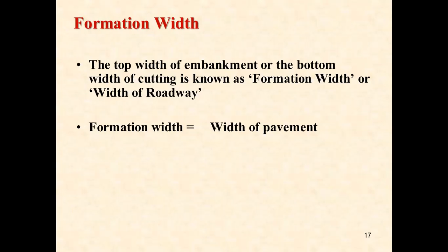So we have to go for land acquisition, and we have to give compensation wherever property is there, for the facility where we extend the roadway. So this is going to occur. That's why we take into consideration the future of 5 to 10 years. The formation width is acquired. The land is acquired for the total width of the formation, which we call the width of the roadway. So for the future also we take this into consideration. Then we acquire the land to go for the new highway project.